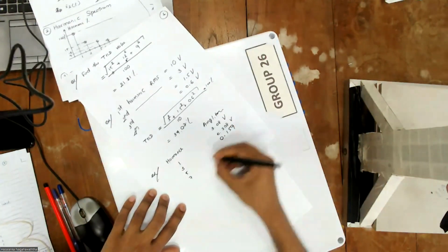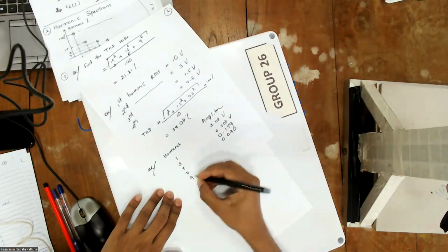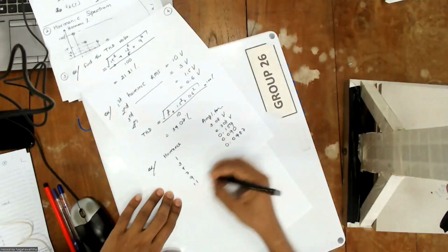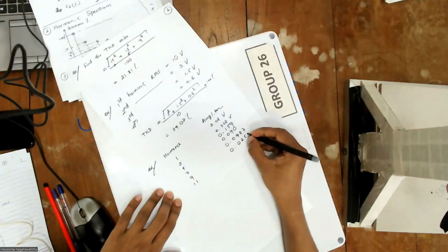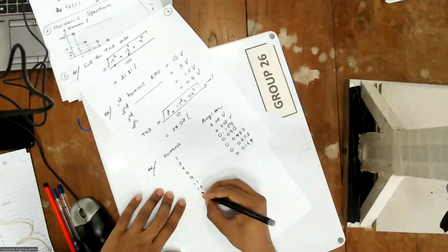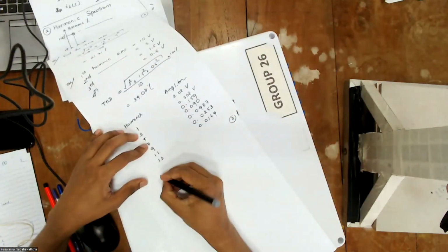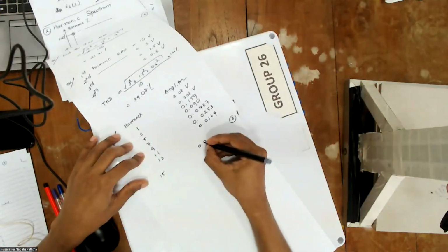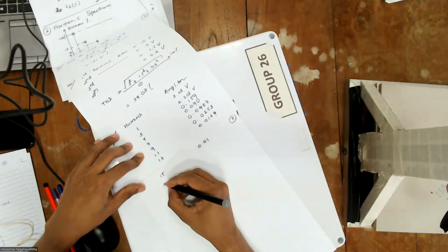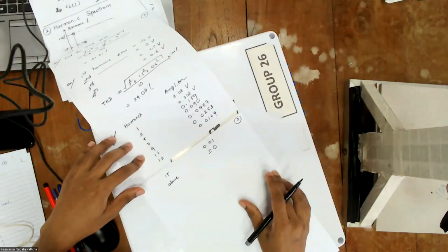Seventh harmonic 0.090, and ninth harmonic 0.0487, and 11th harmonic 0.0253, 13th harmonic 0.0164, then the 15th harmonic is 0.01, and the harmonics above are more or less equal to 0. Then find the THD value.